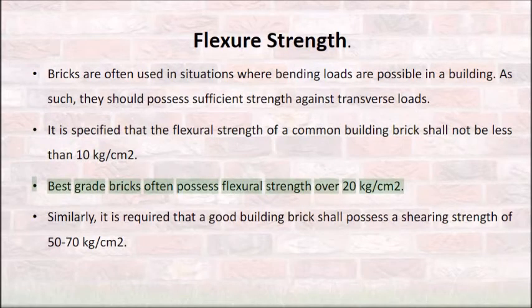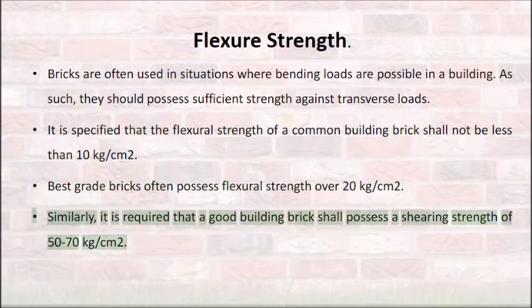Best grade bricks often possess flexural strength over 20 kg/cm². Similarly, it is required that a good building brick shall possess a shearing strength of 50 to 70 kg/cm².